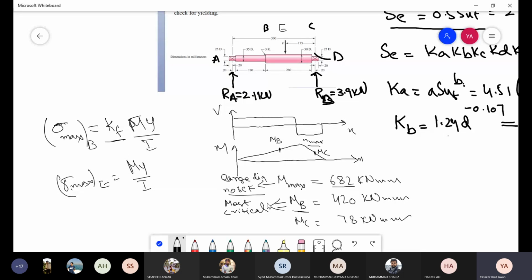It would become more clear when we find the stress concentration factor, because the stress concentration factor is usually around 1.52. So there is not that much difference between their moments, and then there is also the difference in area. Probably we can see that the stresses would be higher at this point. This would be the most critical point. Otherwise, you can calculate that. Okay? If you are not sure, then you can calculate the maximum stresses and compare.